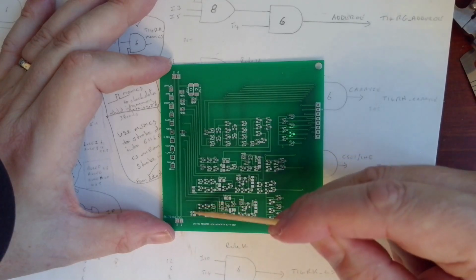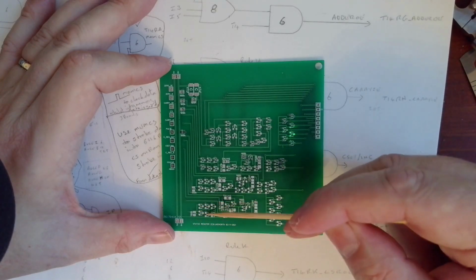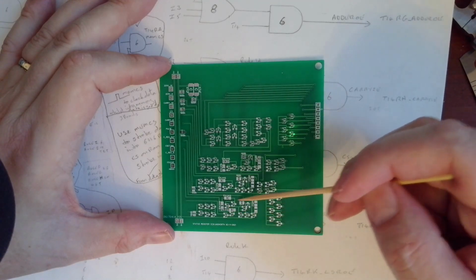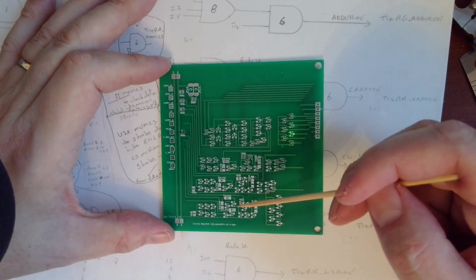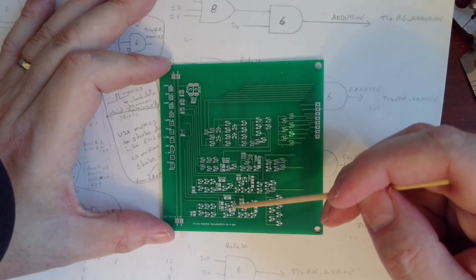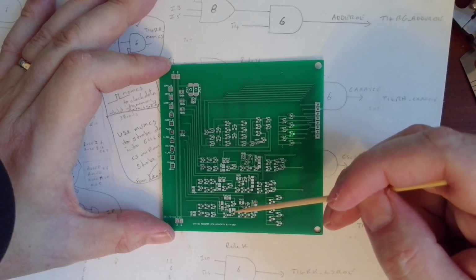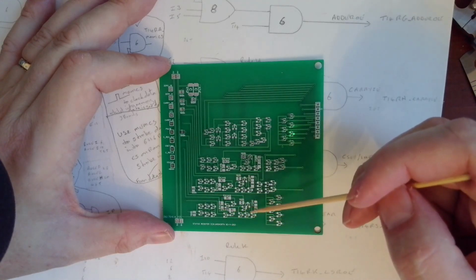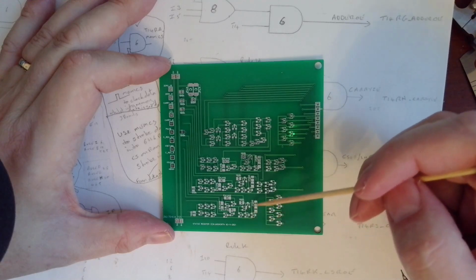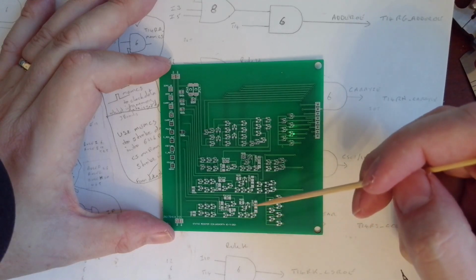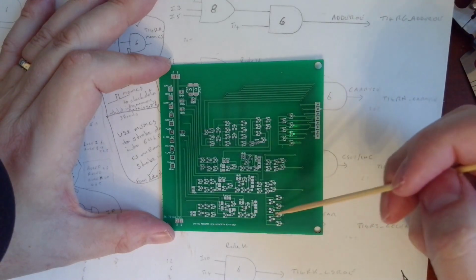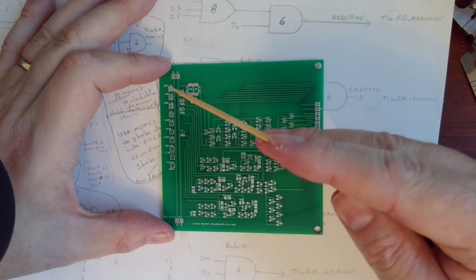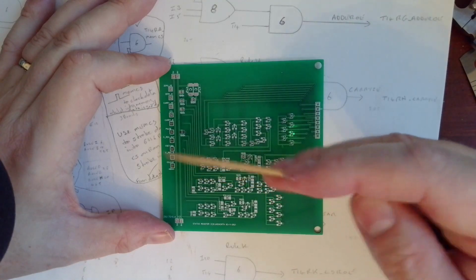Again, there's your AND gates in the pulse for controlling the actual input, and there's the actual memory cell sitting in here. But this one's a little bit more complicated because you've got a pull down MOSFET for pulling it to 0 and a pull up one for making this a 1 for when you need to set it to 0 or 1. The output of this doesn't come over to the data bus at all. It feeds back across out onto the control bus, so there's a C register output up here that goes out.